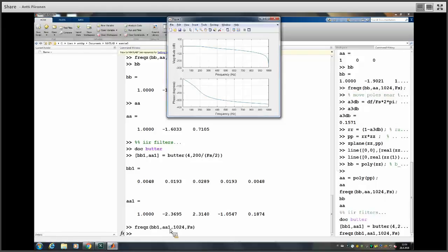scalar corresponding cutoff frequencies is also returned. So now we can use the BB1, but instead of that we put NN and also WN here. So that'll calculate the 12 order Butterworth filter coefficients. And the frequency response of that one is something like that. So our design was to have the 3 dB point at 200 Hertz.